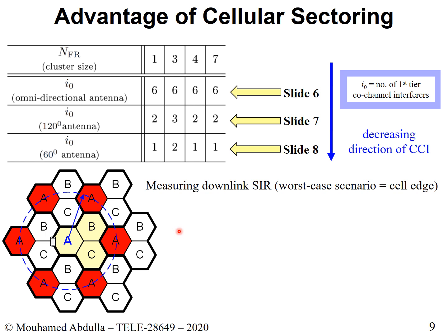Now, the way we do the analysis is as follows. Before we do the analysis, I want to show you the equation for the channel. This is how we will proceed. Essentially, this equation resembles the Friis equation with some modification so that it is specifically tailored for mobile communications. In here, you want to find the power at the receiver. The receiver for us is this device, the power at the receiver, measured at a distance of d away from the base station, away from the eNodeB. D is just some generic variable for that. And it is equal to the power received at some distance d naught.